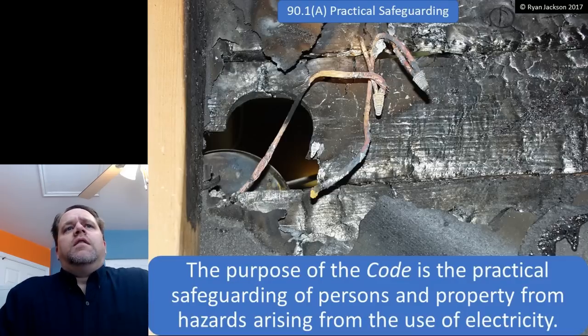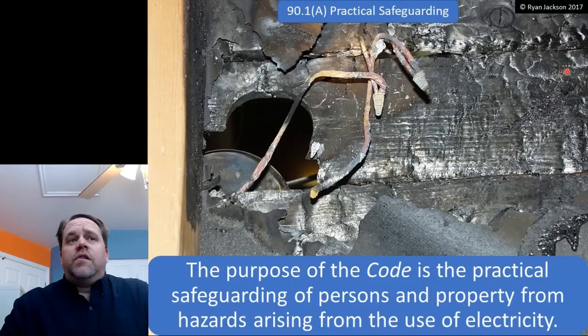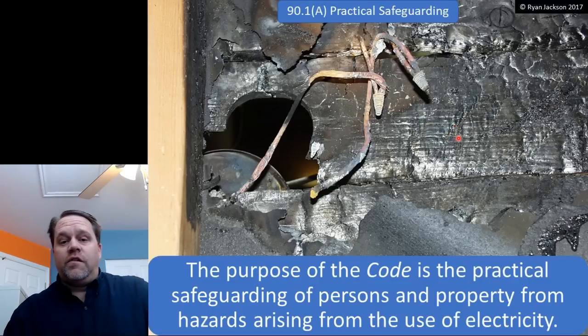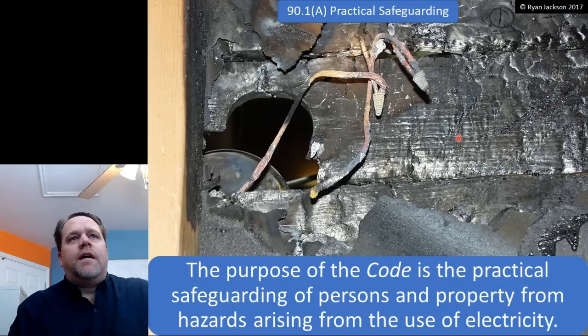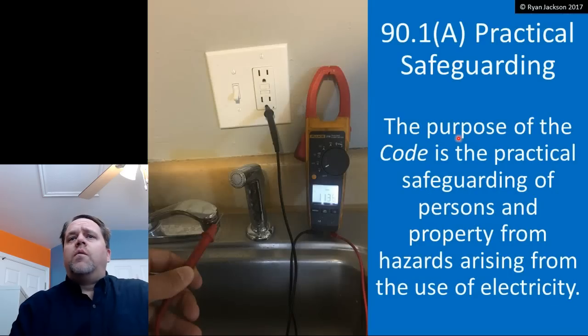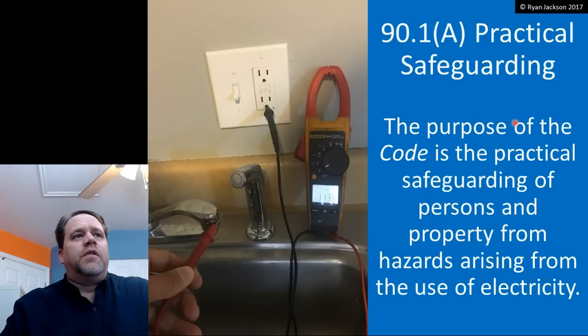So yeah, this low voltage lighting system did in fact start a fire, and that is why the code exists, to prevent such things. This was an open splice. Whoever ran it kind of thought the way the fire marshal did, thinking that it was low voltage, so who cares? And unfortunately, that's not the right philosophy to have. So we have fire from electricity, and we also have electric shock from electricity.